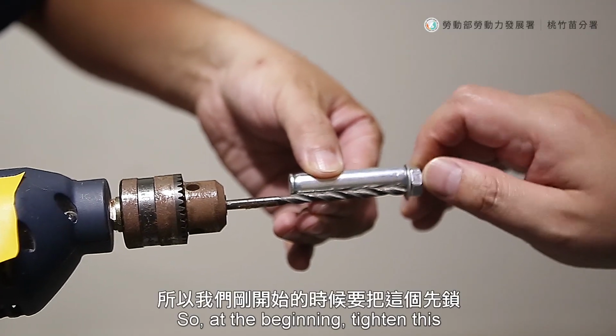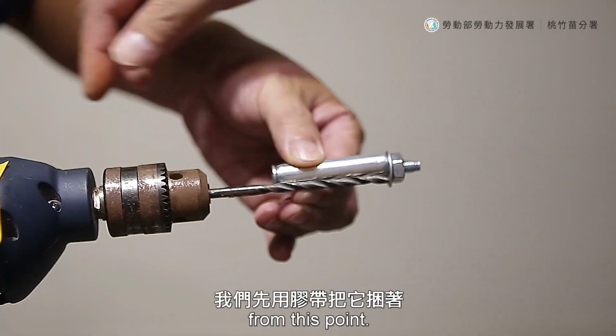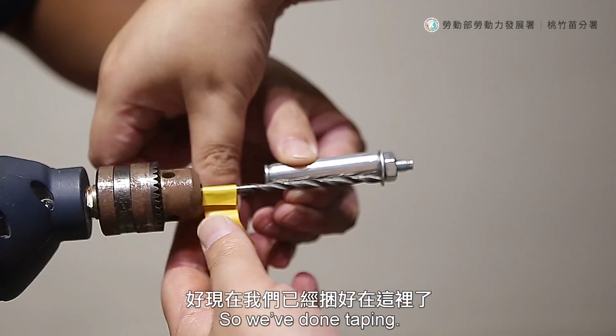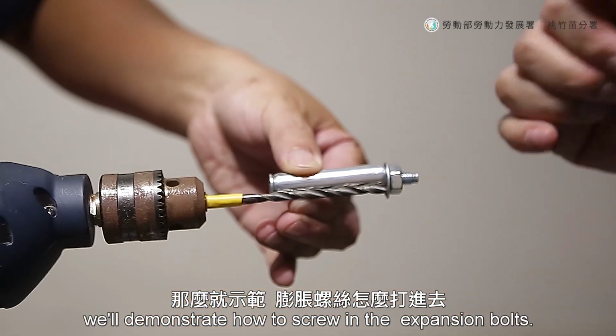So at the beginning, tighten this a little bit. Tape it about 0.5 cm to 1 cm from this point. So we'll know how deep to drill. So we've done taping. It should look like this. We'll demonstrate how to screw in the expansion bolts.